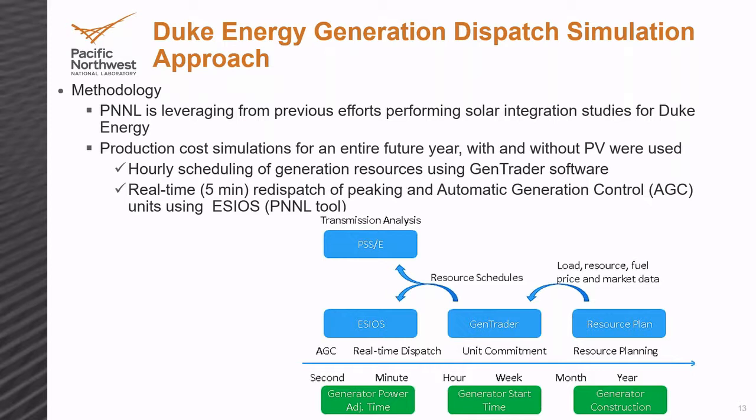And then the next step will be trying to mimic system operation using production cost modeling, which will simply dispatch your resources, your generation, to figure out how my generation will move to meet the demand, given that I have this amount of PV in my system. And you can run a case with and without PV to see the impact of higher PV penetration in your system. So using this, you will end up having one snapshot of your system every hour.